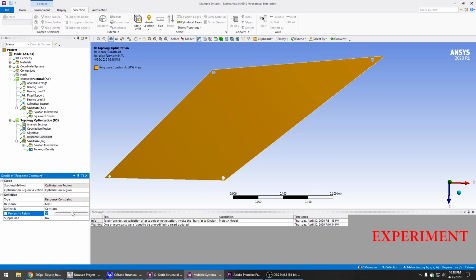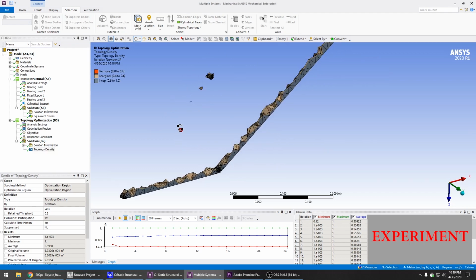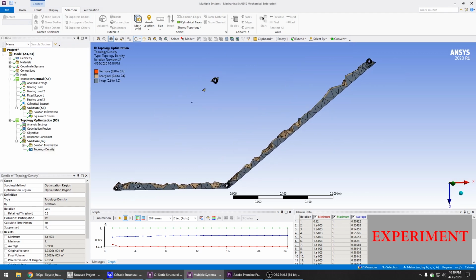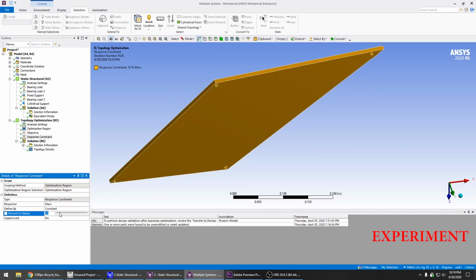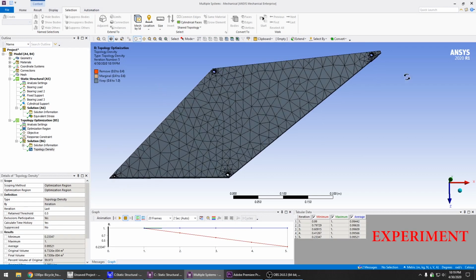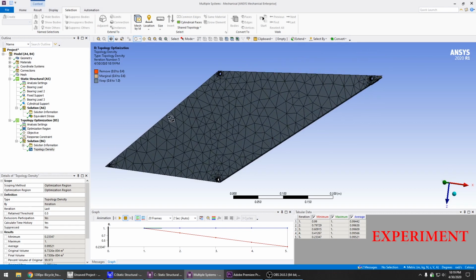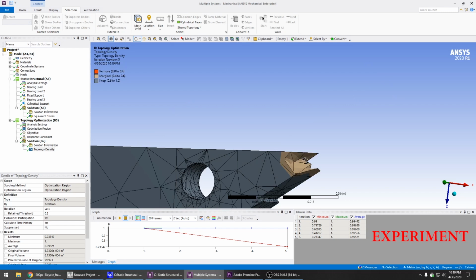8% to retain, let's try, if we put it at like 12%. Yeah, there you go. See what I mean? It will go to this extreme where it nearly removed our constraint. Start at 50%. If I leave it at 100%, it won't do anything at all. There we go. So at 99%, it converged on a solution and it didn't do anything other than chop the corner off.